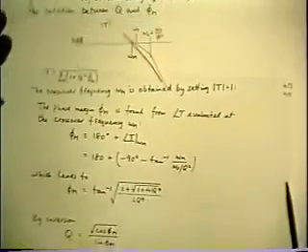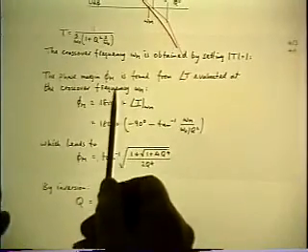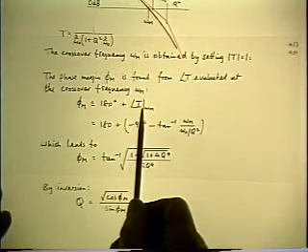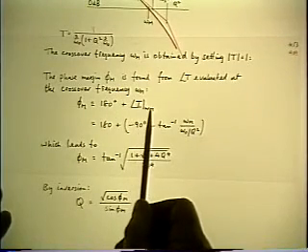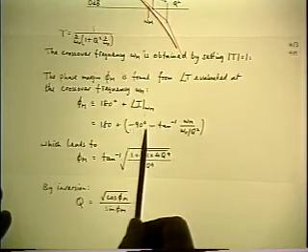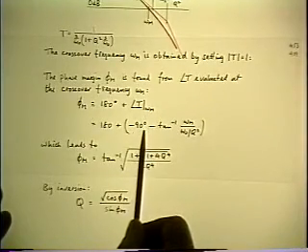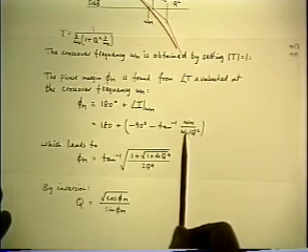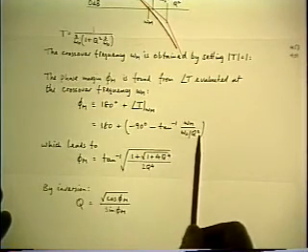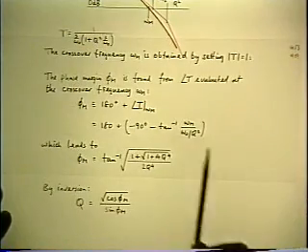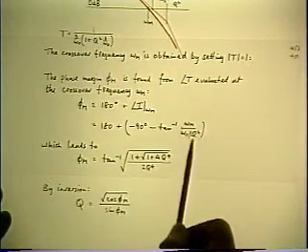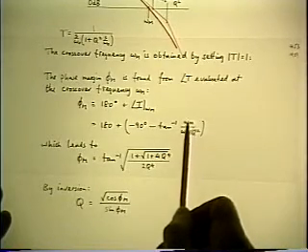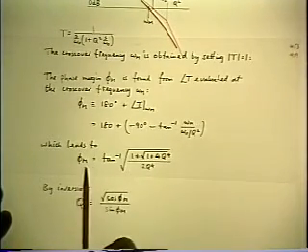and now you evaluate the phase margin, which is 180 plus the angle of T evaluated at the crossover frequency, which is minus 90 degrees from the first asymptote, and then minus arctangent of the crossover frequency divided by the second pole. It's how you find any phase angle from a single pole function. This is the omega 2. And when we substitute for the omega m that we just solved for, you get this.